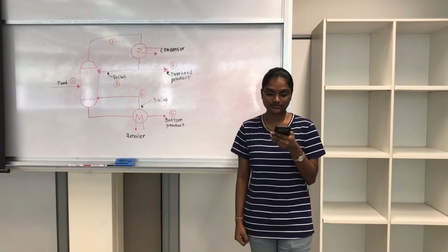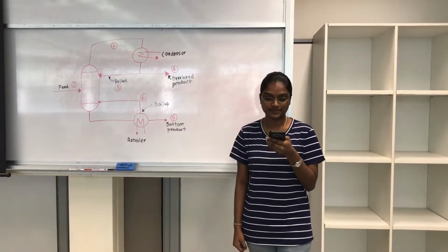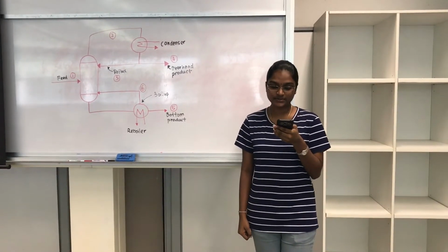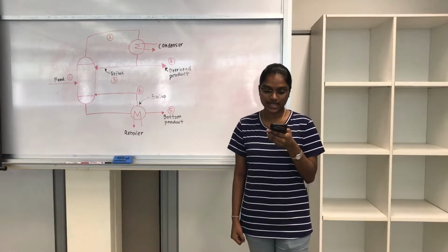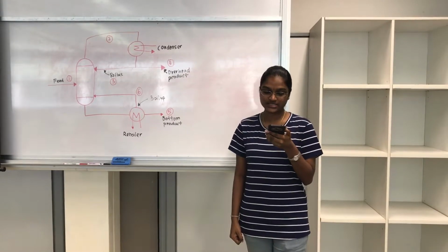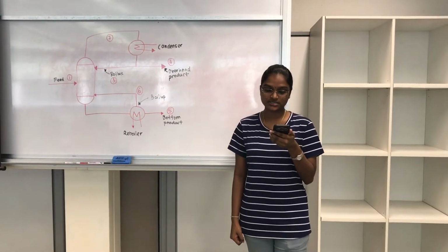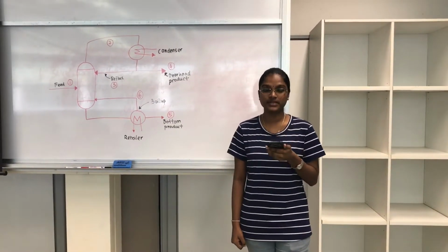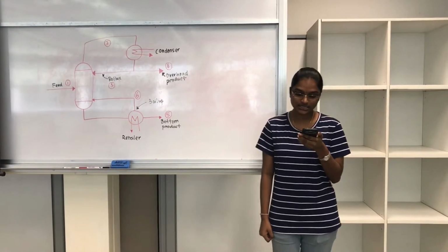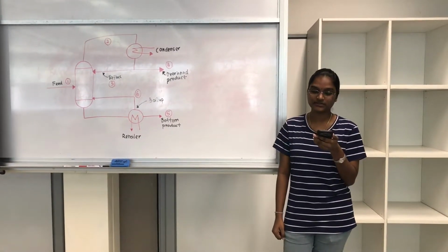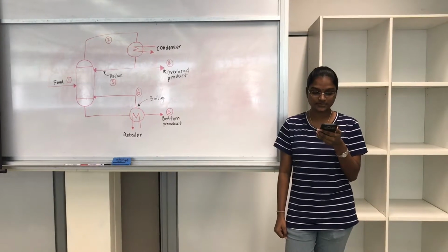Mixtures with high relative volatilities are easier to separate. This makes separation of close boiling and azeotropic feeds difficult. So special distillation techniques have to be used to separate these mixtures. Distillation can be used to separate binary or multiple component mixtures.